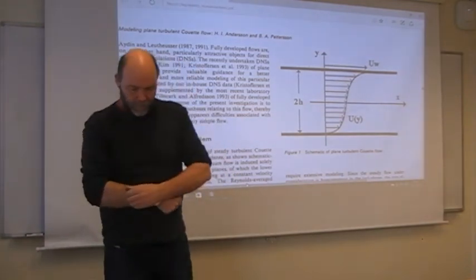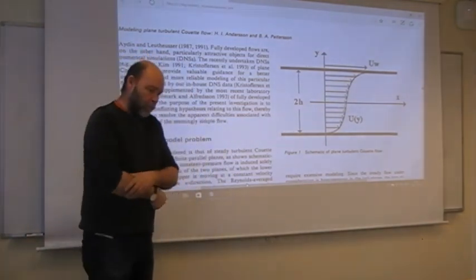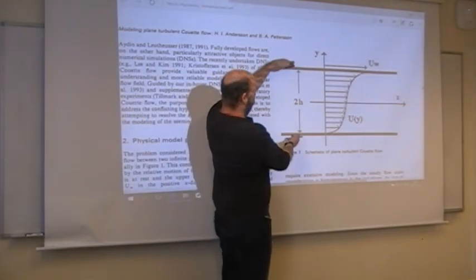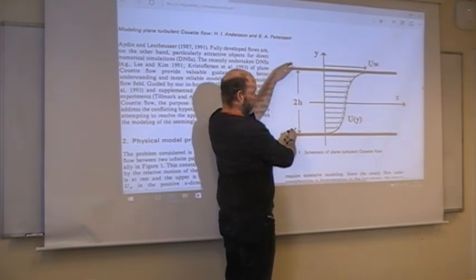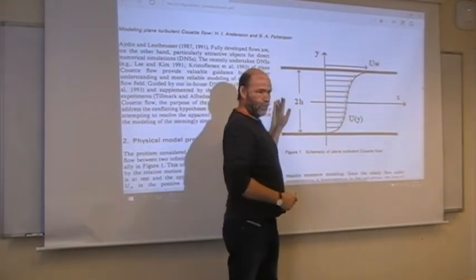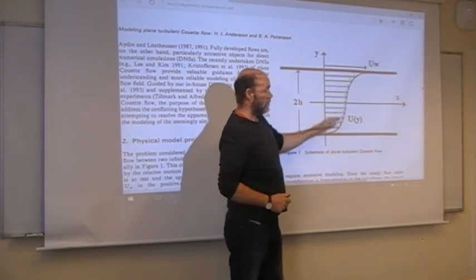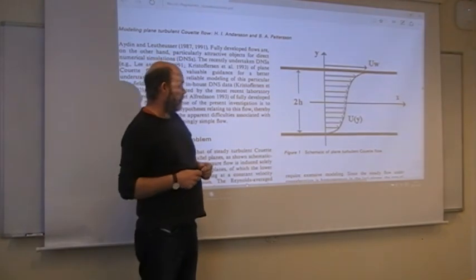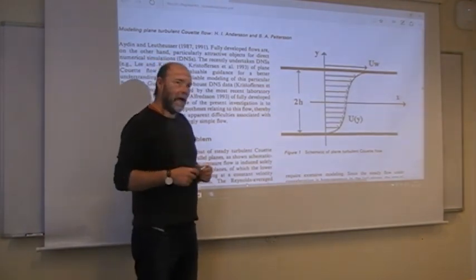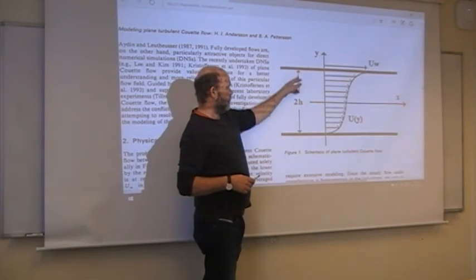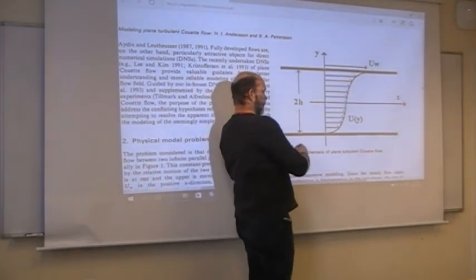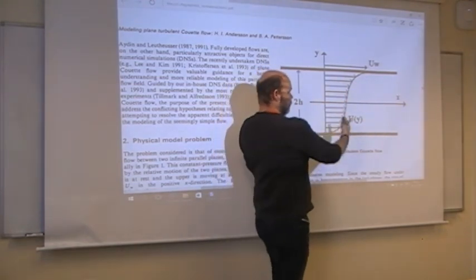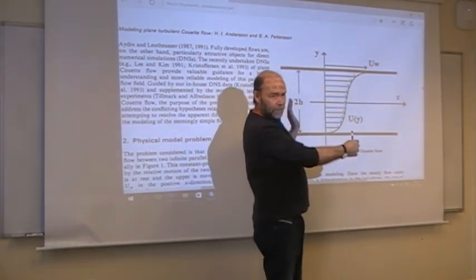As a contradiction to the Poiseuille flow. For the Poiseuille flow, you keep both walls fixed, and then you set up a pressure gradient or gravity as a driving force. What then? Well, before you begin, you can calculate the wall shear stress. Because if you look at a control volume inside your entire computational domain, then you can set up a control volume analysis, take a force balance.